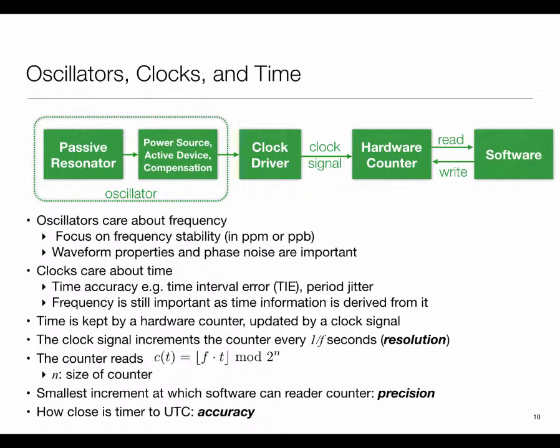Kind of things that you really care about out here is really what kind of waveform I have. There's something called phase noise, which refers to how jittery the edges of the clock are. So I may have clocks which on average have a particular frequency, but every clock edge may have tiny amounts of error in it. Okay, so there are many different ways of looking at it. One of them is how noisy the phase is. That is, if you compare it against a stable clock, you would see that the phase difference is going to have noise in it.